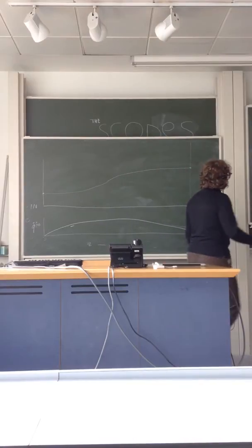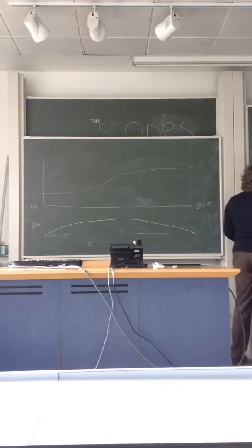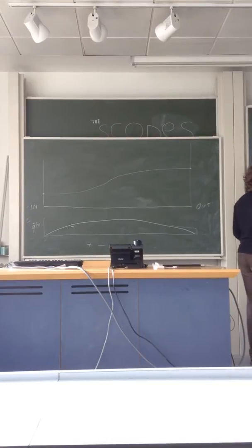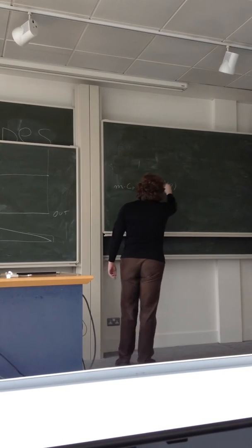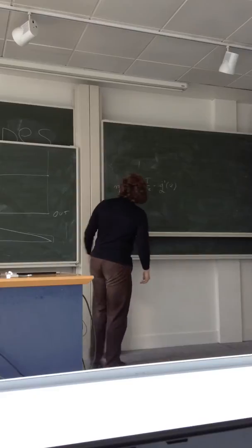Now, mathematically, you have a fixed mass flux of coolant times its heat capacity, which is the same for liquid water, a little different for gas, times, if I remember correctly, dT over dz, z being vertical distance up into the core, would equal q prime as a function of z. This is some sort of a cosine function, and on integration we obtain this temperature profile.